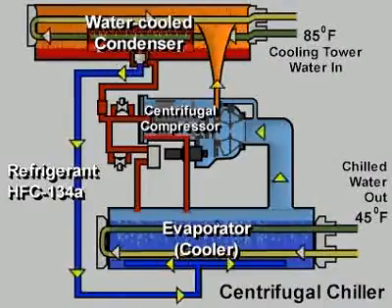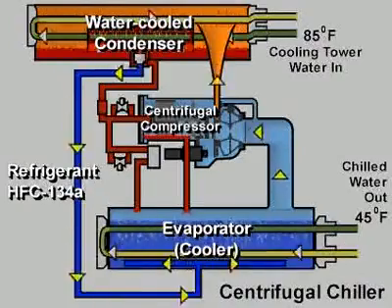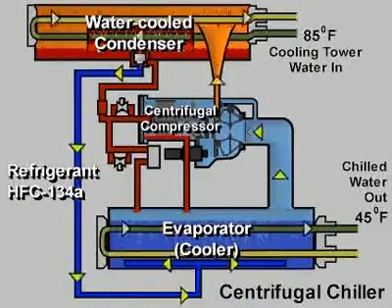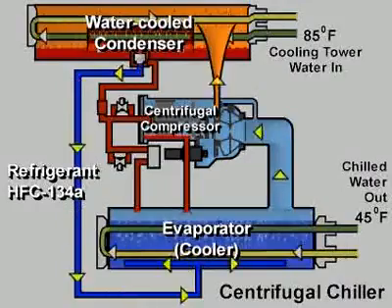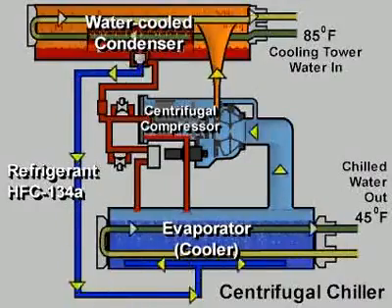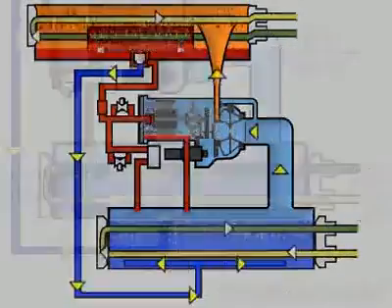Refrigerant pressures and temperatures vary widely based on the type of tubes in the heat exchanger, whether brine or freshwater solution is used, the pass arrangement on the heat exchanger, and the water flow rate. Values are normally found in the chiller design data specifications.